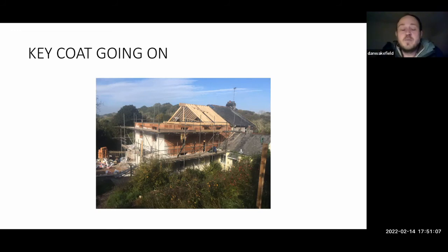So we've been waiting to be able to airtight the junctions between the roof, the ceiling, and the walls, and where the internal walls abut the external walls, we've had to leave gaps everywhere to allow the plaster to dry before we could tape to them. So that's been something that's been difficult, a bit of a wrestle, really.